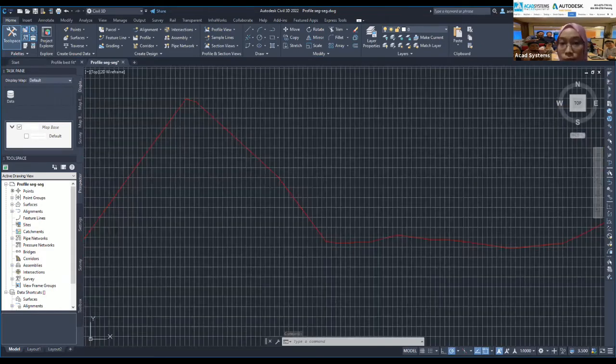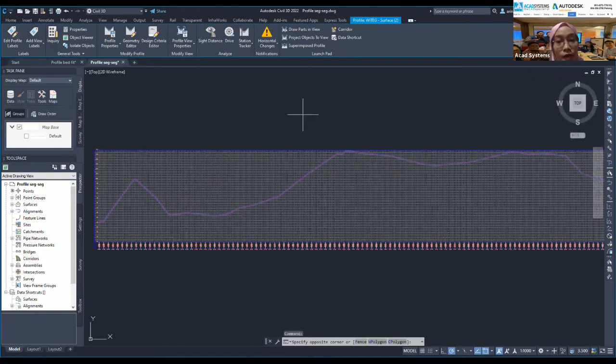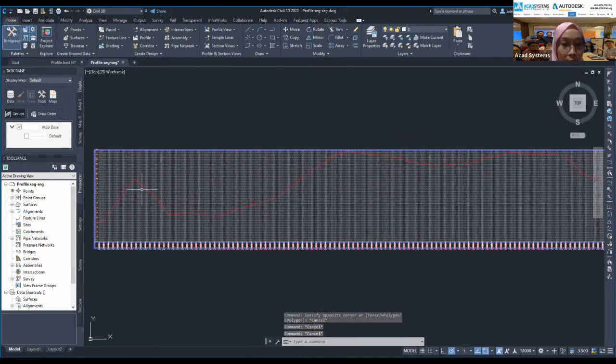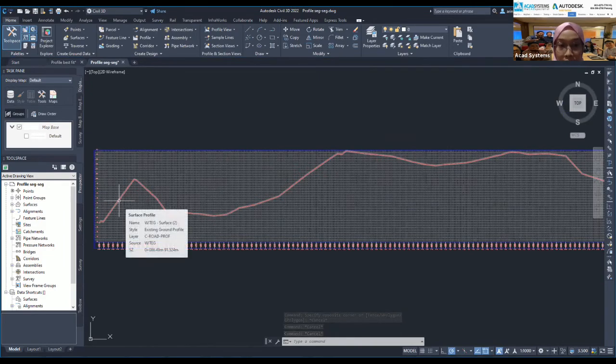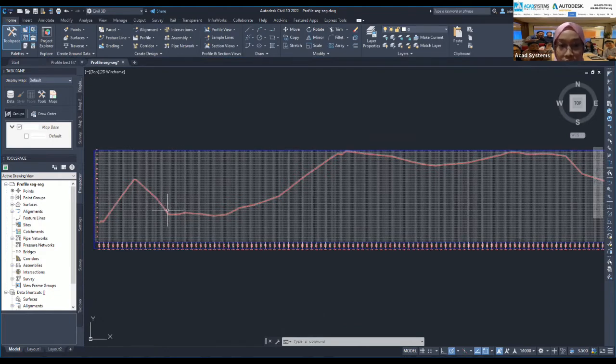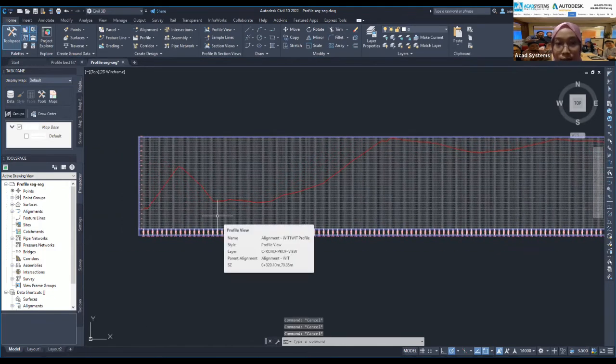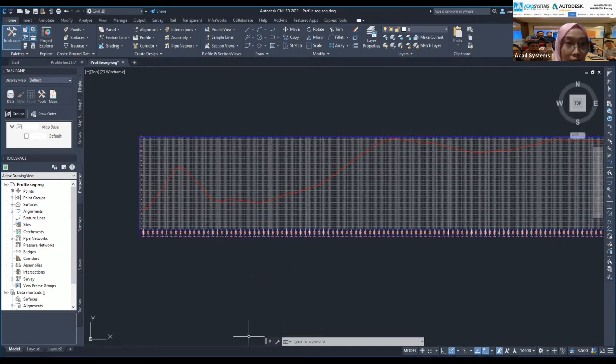For instance, the red one is our profile. What I'm going to do is on the curve here, we're going to create separately for the curve. We're going to create a new profile for each curve. So that is why it's called segment by segment. Okay, so to create the profile curve by curve or segment by segment is again under the Home tab here, you have the profile.